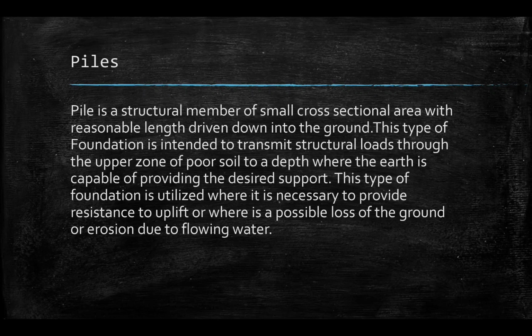So, pile is a structural member of small cross-sectional area with reasonable length driven down into the ground. This type of foundation is intended to transmit structural loads through the upper zone of poor soil to a depth where the earth is capable of providing the desired support. So, yun yung tinatawag nating hard soil or hard strata. This type of foundation is utilized where it is necessary to provide resistance to uplift or where there is possible loss of the ground or erosion due to flowing water.